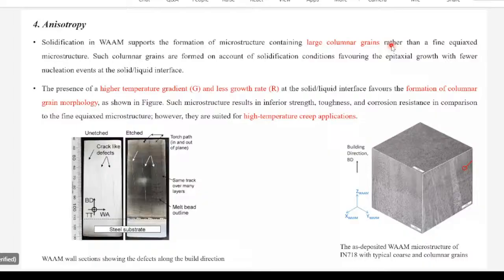So that is the continuity in the microstructure region. If we take a specimen out of a cross section and check the microstructure, we can check that continuity, those columnar grains. You can see here the transition zone. The columnar grains are growing in the upward direction, along the z-axis motion. So this is known as epitaxial growth.